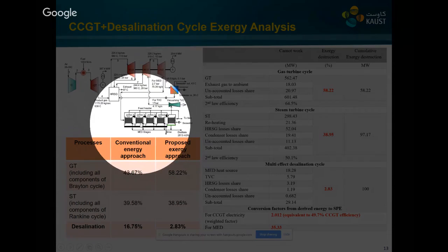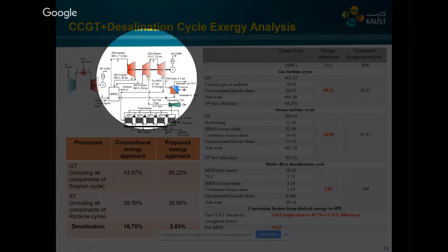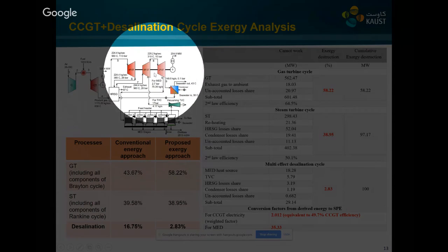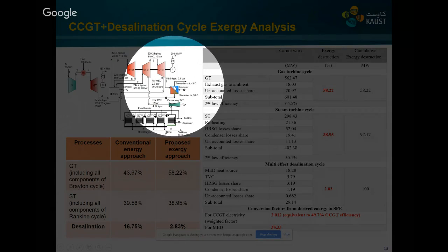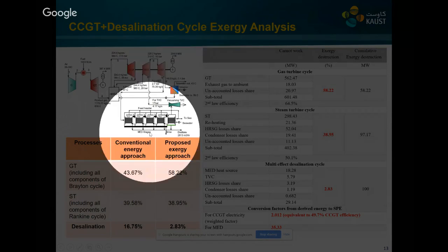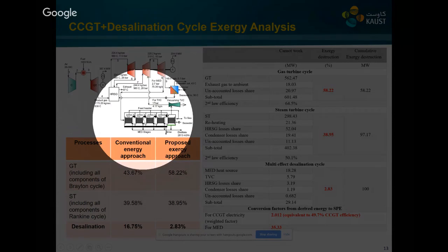But the integration of the thermal system with the power plant has a very good synergy, because if we look carefully, the steam that is bled from the last stages of the turbine has already performed most of the job. So this is almost a dead steam. Just before going to the condenser, where it would be condensed, it is extracted and utilized in the desalination cycle.